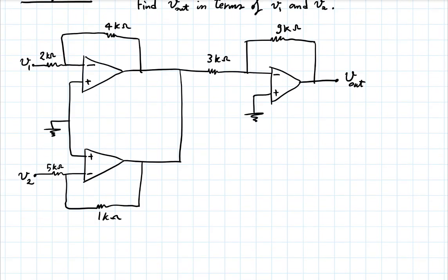Well, again, you can write all the equations, but like the kind of things that we saw yesterday, let's start by putting down whatever we know. So this is 0 volts here, which then gets transferred to other pins because the two inputs should not have a voltage difference. And in fact, same here. And we know that the op-amp does not draw any input current, so we have 0, 0, 0.